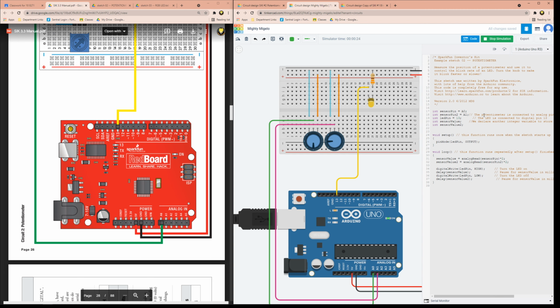Right. So that's this tutorial over here. What did we learn? We learned that when you are doing variables, you have to define it as an integer. Then for your digital pins, you have to tell the Arduino whether it's going to be an output or an input. For your analog sensors, you can just put in the value in there, and it's going to be a value between 0 and 1024, depending on whether it is a value of 0 to 5 volts.